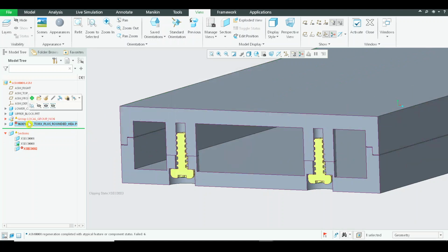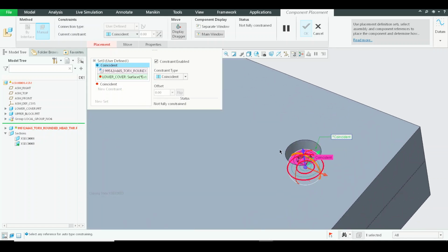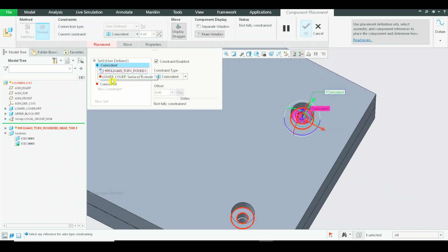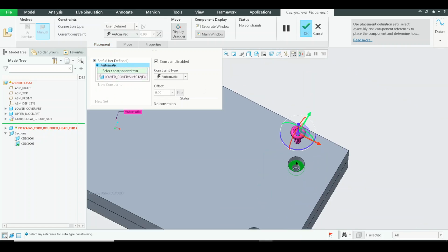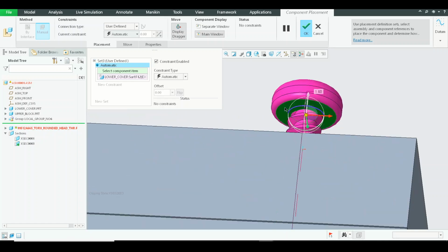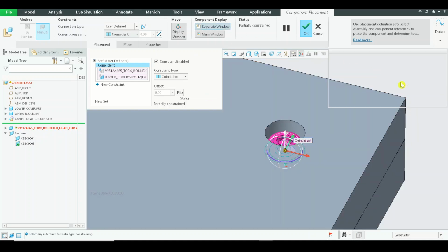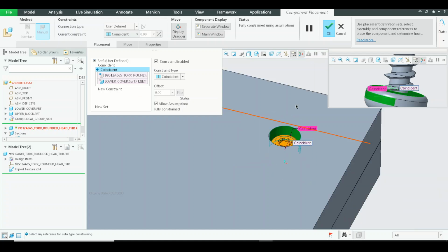All right, I'll delete the first screw we have downloaded, 0.25, and for these screws I will be adjusting the constraints. So the lower cover is deleted. I'll select remove, delete. This surface will be in contact with this surface and they will be coincident to each other. Okay, open in separate window. This surface or this cylinder will be coincident with this one. Press OK.